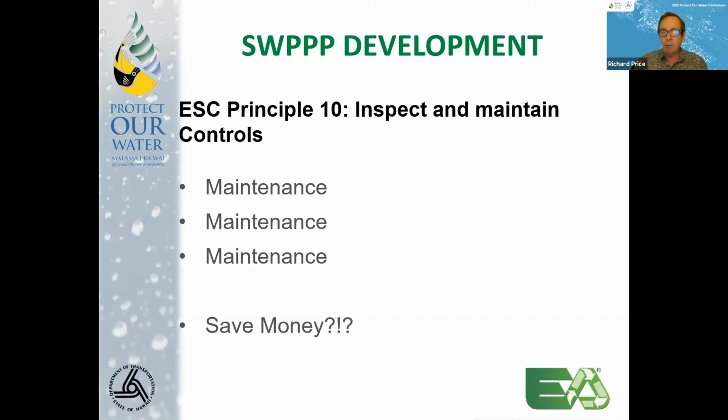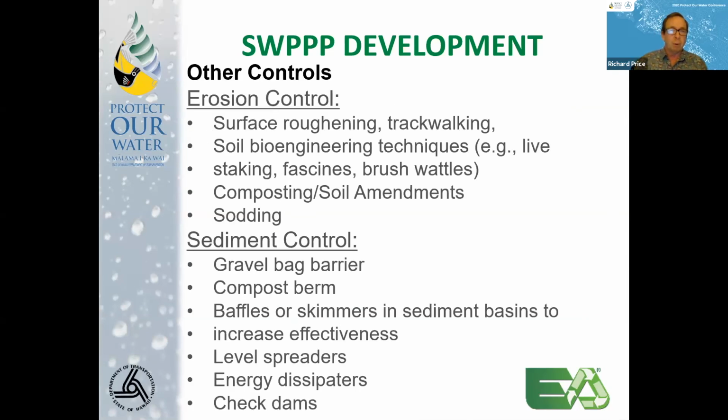So putting a little thought into what you're putting in: how long is it going to be there? What am I going to have to do to maintain this, clean the sediment that collects there, and how might I do this better? Are there ways to minimize the actual erosion so we don't have as much sediment to manage? Can be a huge money saver over the course of a project.